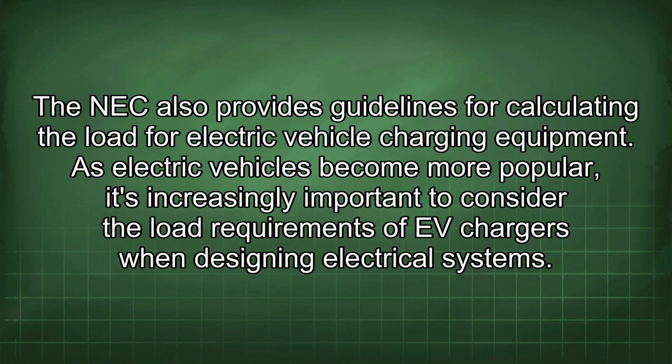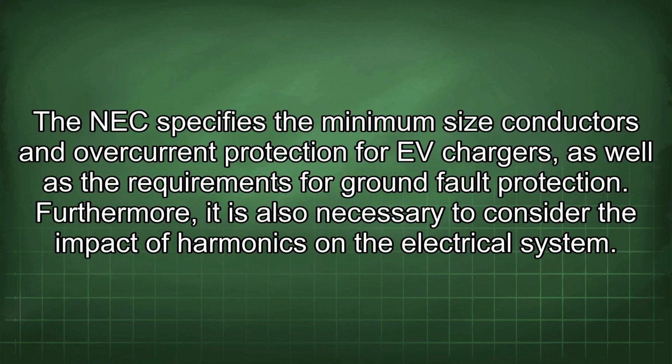The NEC also provides guidelines for calculating the load for electric vehicle charging equipment. As electric vehicles become more popular, it's increasingly important to consider the load requirements of EV chargers when designing electrical systems. The NEC specifies the minimum size conductors and overcurrent protection for EV chargers, as well as the requirements for ground fault protection.